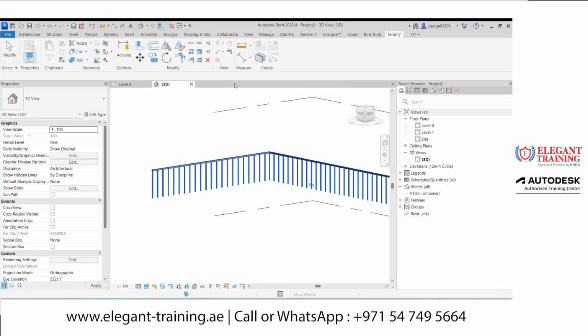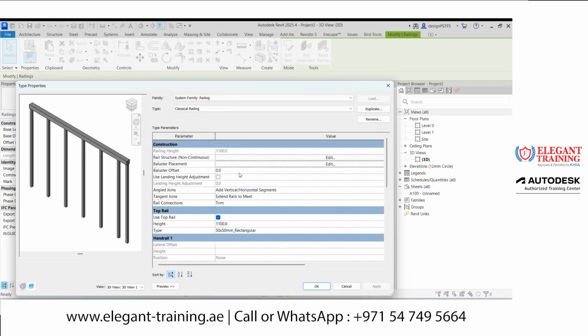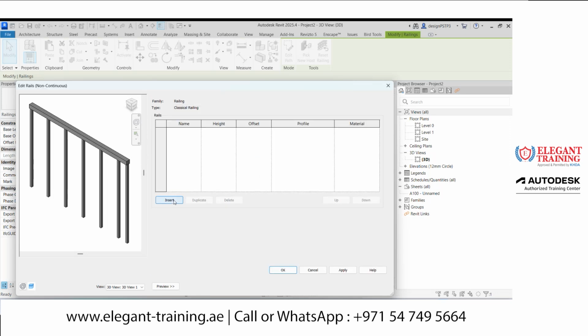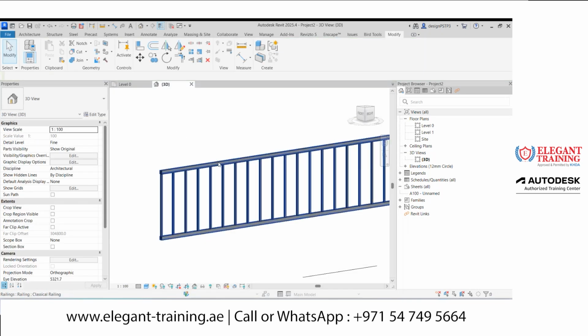Let's close all this family and let's assemble this one. So let's go to edit type. Okay, and let's go to the baluster placement, rail structure, and from here I'm going to add 2, and I'm going to name this one as the top rail and this one as the bottom rail. Okay, and the height of this top rail will be 1100 and the profile. From where can I get this profile? See, right now it's not loaded here. Correct. So let's give this one OK. By default, the default thing will come, but we will come back and change it.